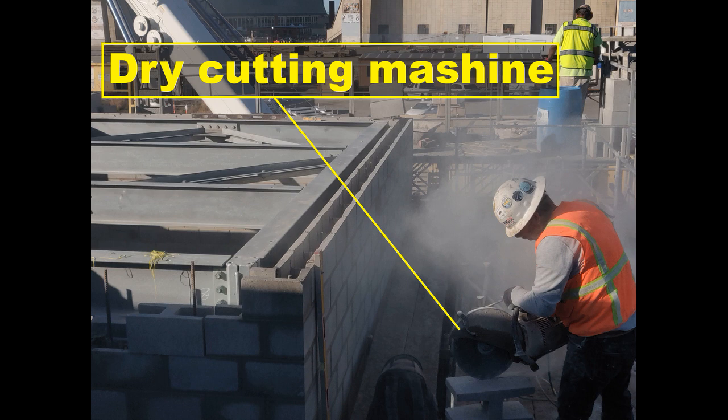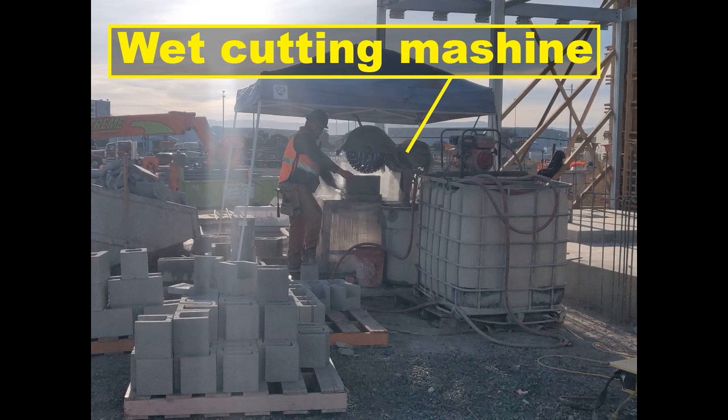Cutting and fitting. Use full units of the proper size wherever possible, in lieu of cut units. Locate cut units where they would have the least impact on the architectural aesthetic goals of the facility. Perform cutting and fitting, including that required to accommodate the work of others, by masonry mechanics using power masonry saws. Concrete masonry units may be wet or dry cut. Before being placed in the work, dry wet cut units to the same surface dry appearance as uncut units being laid in the wall. Provide cut edges that are clean, true and sharp.